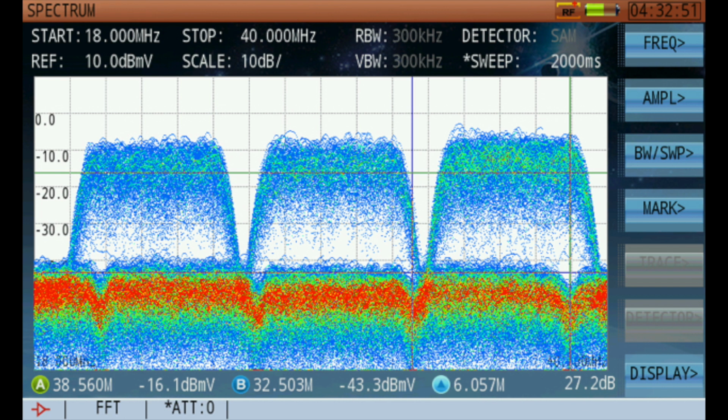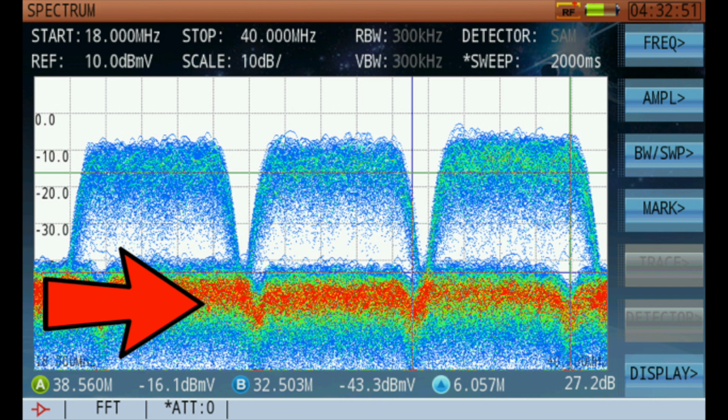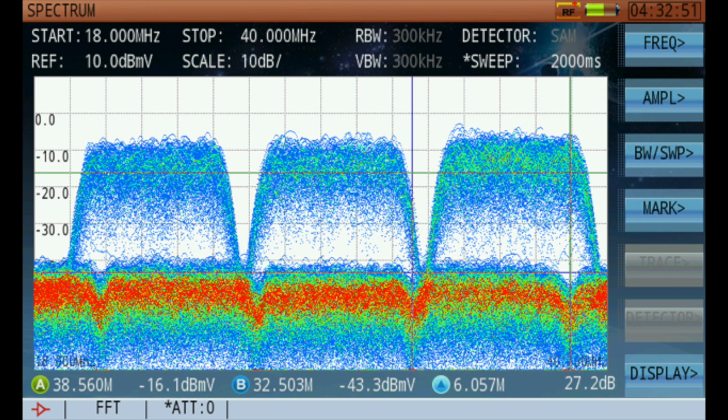This allows some of the FFT scans to capture the RF signature where the desired signal is not transmitting, then revealing the noise floor below and an undesired impulse noise or linear distortions that might be hiding below. Once the sweep time resets, multiple FFTs will have been overlaid, one over the other, thus showing both the desired and undesired signals simultaneously.